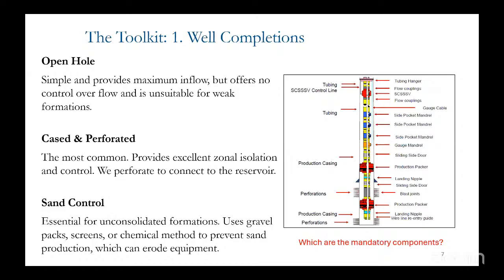Yeah, you tried. So the ones I think that are very important, we have the packers, which is very important. We have the sliding sleeve doors, very important. We have the SSSV, safety valves, very important. We have flow couplings, very important. And we have nipples in case of interventions and the rest, very important as well. Yeah, I think that should be sliding sleeves. And the side pocket mandrel is important if we were to go into an artificial lift method, like to inject gas into the well. If there's possibilities for that, so that's very important as well.